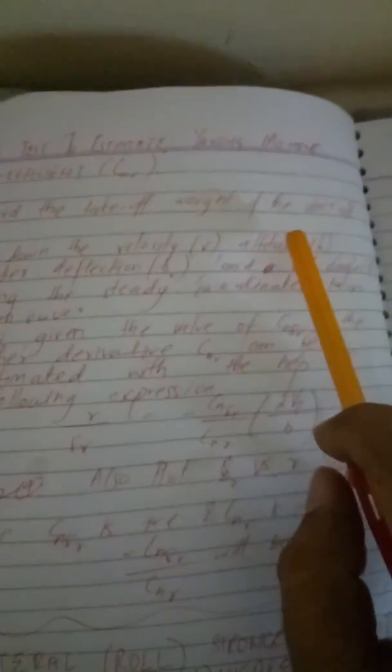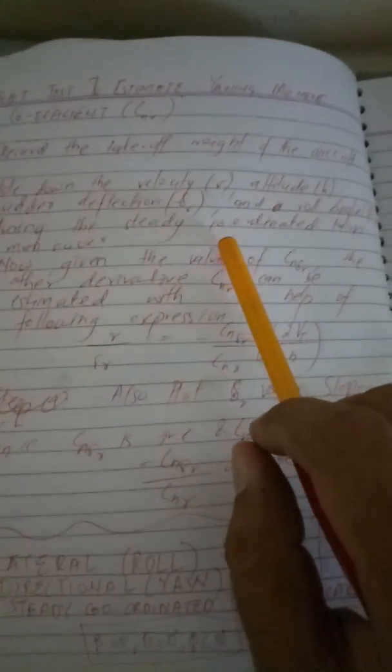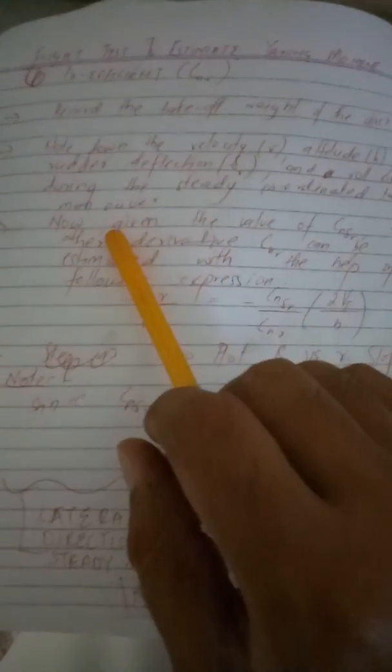Obviously the assumptions must stand, so that we can say our equation and the flight test are absolutely okay according to the International Standard Atmosphere. That is why we have to take a test, just to check that what we have assumed is right according to the standards. First of all, record the take-off weight of the aircraft, and note down the velocity v, altitude h, rudder deflection delta r, and roll angle phi during the steady coordinated turn maneuver. Okay, we have to consider this with the help of the instruments we have discussed earlier.